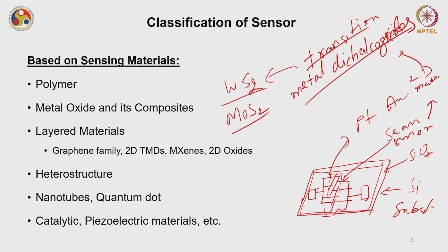Say I am typically coating this interdigitated electrode with tungsten sulfide or some metal oxide which has a semiconducting property. So this is a typical structure of a gas sensor, a two terminal gas sensor. We will term it a chemi-resistive sensor. We'll discuss that in some time.